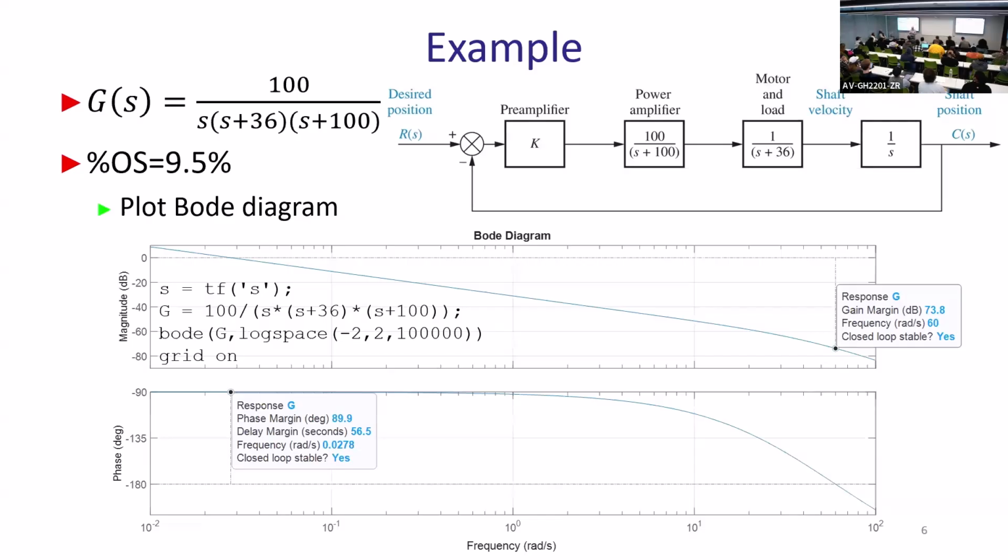All you're looking at in the Nyquist theorem is encirclements of the -1 point, right? So what is -1? What gain do you have at that point? It's 1, which is practically 0 dB in a Bode diagram. And what is the phase that you're handling here? 180 degrees and all the multiples of that, the negative axis. Every time you cross that point, this is a 180 degree crossing in Bode diagrams. When gain crosses 0, this is exactly that point that you're encircling.